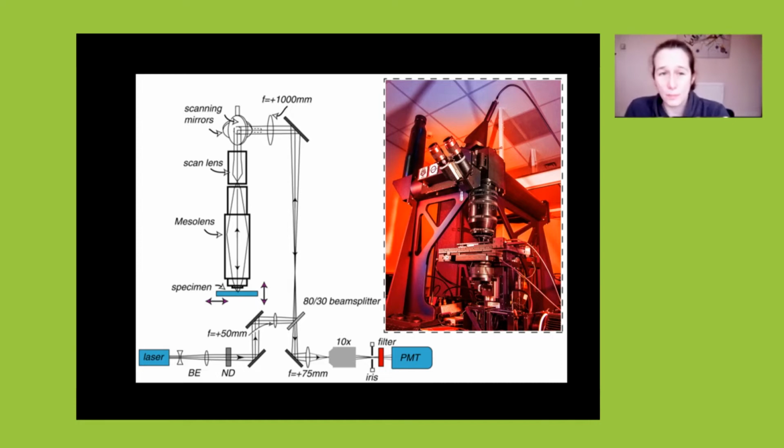Ours are around the same size as a car wing mirror because we need to backfill and overfill the back aperture of the scan lens, and that has an opening of around 60 millimeters or so, hence the car wing mirror-like approach. We use lightweight back-thinned beryllium mirrors, and they have almost enough precision and repeatability.